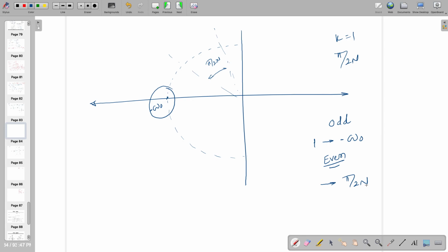In the case of third order, you will get a difference of 60 degrees, because from here to here it's 180 degrees, right? With real and imaginary parts, you can find out where they are lying. So if you are keeping your poles on this unit circle, normalized with the center frequency, then that approximation is the Butterworth approximation, and that is going to give you a maximally flat response. This is what Butterworth has told.